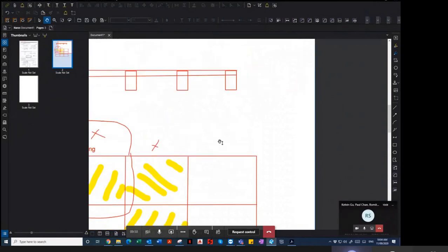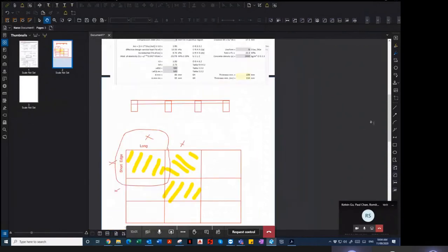Okay. So what happens is, if we're looking at a simply supported beam, then our moments are like that, isn't it? So as soon as we go towards the end, we tend to have zero moment. In reality, with concrete structures, there is some moment over here. It's very small though, but you do have some moment.